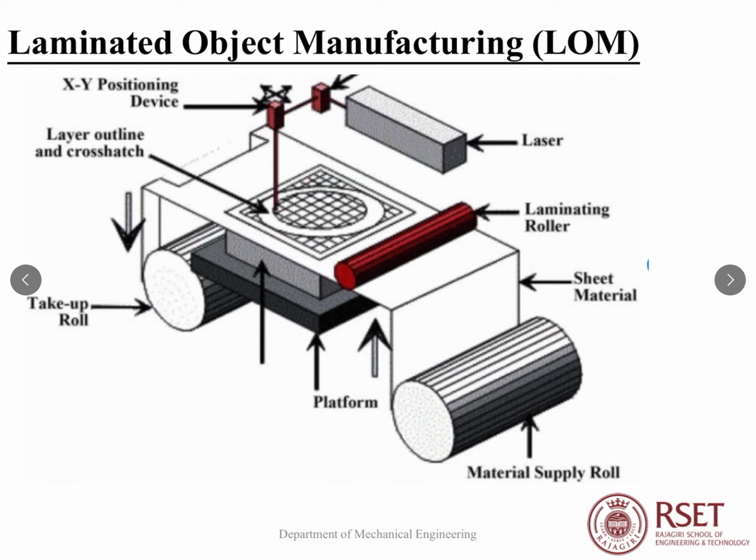So that is about selective laser sintering. It consists of two bins: one is the powder bin, and another is the build area. The powder bin contains powder, along with a blade or roller that acts as a filling blade. By its action, the powder gets filled in the build area, and using the CO2 laser, selective laser sintering takes place. This process continues till the final layer is sintered.